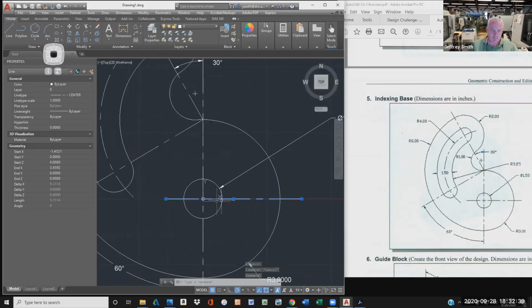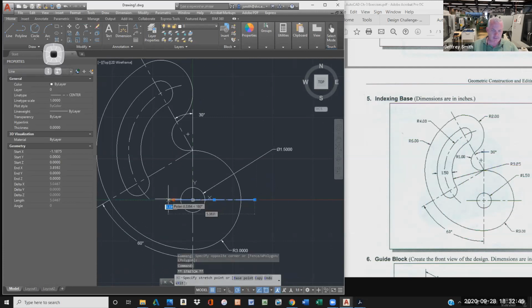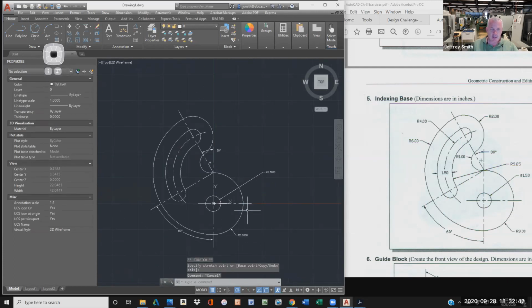You typically want a little bit more. I can massage this a little bit to try to get that gap right in there, but I think we're okay. It says a center line, so I know that. Now I can just start dimensioning this. The other thing I can do, if you're lazy like me, is join. Type in join. I'll select these outer lines, because with your parts, you want to make sure that you differentiate them.